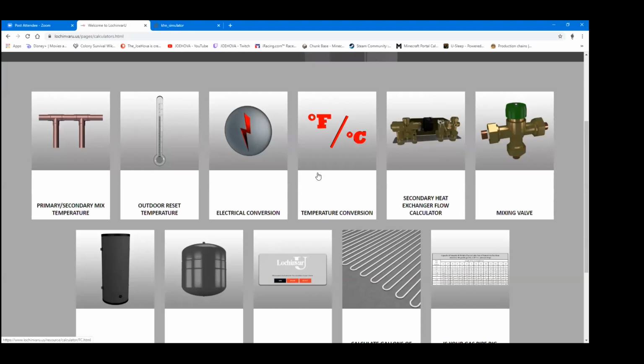So if it reduced the output because they had too much glycol, it didn't really hurt us. But the low pH that's created through heavy glycol in systems really causes havoc on your systems, but really on those heat exchangers. They're not designed for that extremely low pH. And so when people think they have 30% mixtures in their systems, we go out and test, and a lot of times we're over 50%, even in relatively warm environments.